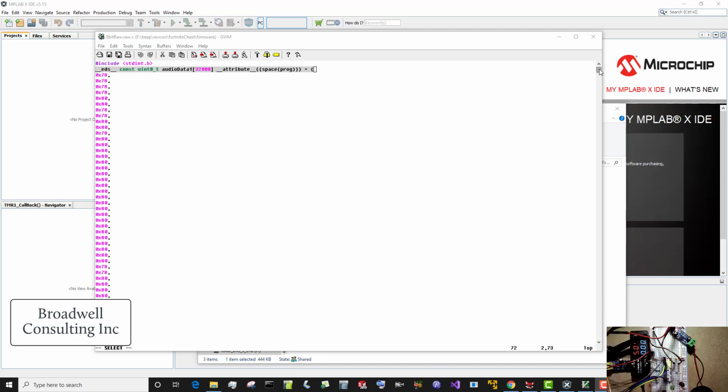In our last video, we created this array, which is a series of sound samples at 16,000 samples per second. Each one of these represents one part of the sound, and we want to be able to play these out over a Microchip PIC. Since the last video, I've modified this file a little bit with some compiler directives.